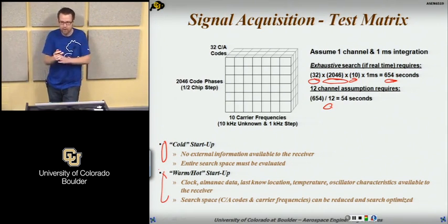We have the orbital parameters transmitted as part of the data message, accurate for that one particular satellite, and that is called the ephemeris. They also transmit something called the almanac, which is a coarse estimate of the orbital parameters for all the satellites in the constellation. So once you have decoded the data from one satellite, you can figure out roughly where all the other ones are.